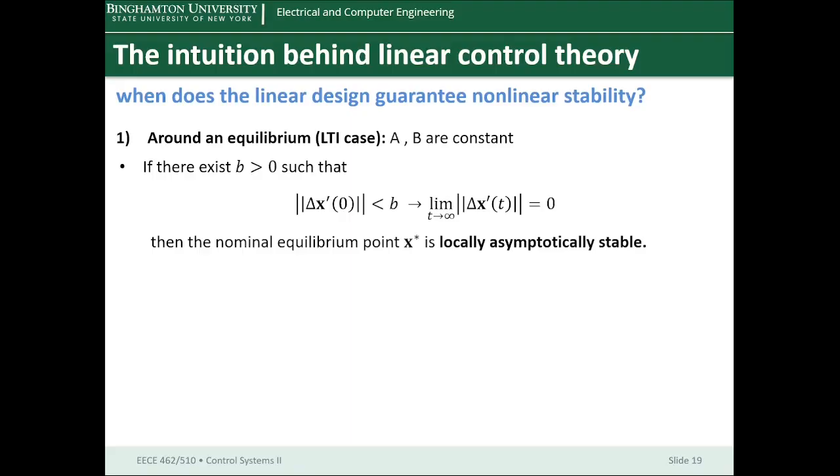It means the high order term converges to zero, or it means the high order term, that is an infinite series, doesn't diverge. So this means the nonlinear closed loop system is locally asymptotically stable near the equilibrium point, or it's locally asymptotically stable.